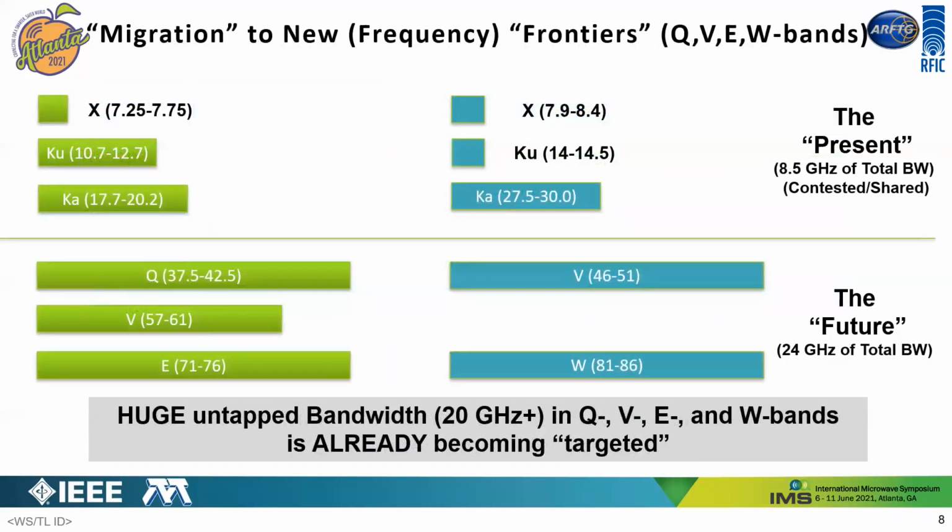Okay, another important design consideration and trend is selection of the frequency band of operation. C, X, and Ku bands have been the traditional bands of choice over the past decades, and they certainly are not going away, though a portion of C-band was recently repurposed for terrestrial 5G use. However, over the past decade or so, Ka band has enjoyed increased adoption based on its shorter wavelengths, which in principle allows for smaller sized antennas on both the user and satellite ends, but at the expense of increased sensitivity and potential outages in heavy weather and rain.